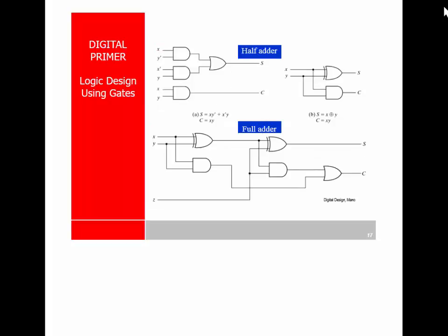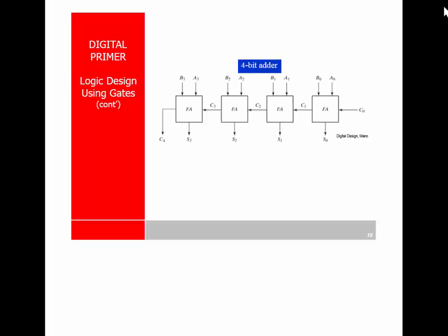So, okay, these are some basic logic circuits. I just did this one right here. This is our basic half adder, and you can see the same circuit if we did it without the XOR. You can see that we went from 4 gates down to 2 gates, so the XOR saves some time. The full adder they don't even show here, but again you can see that that's now 5 gates to do a full adder.